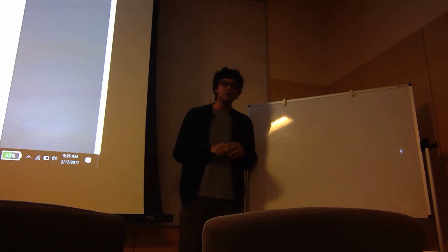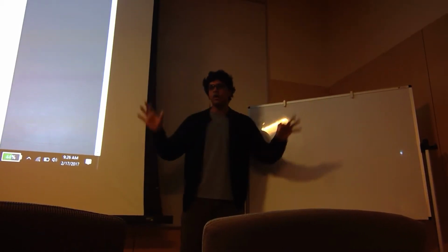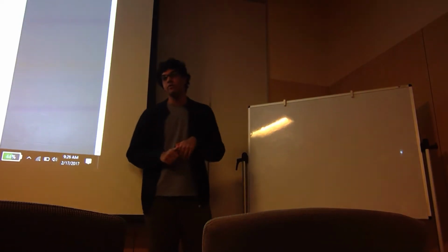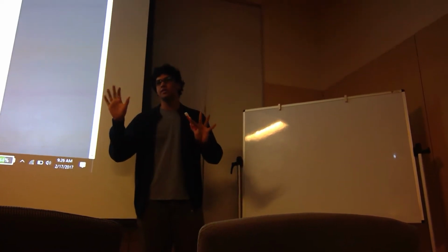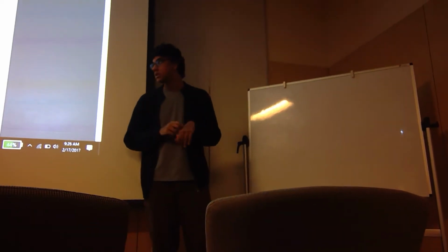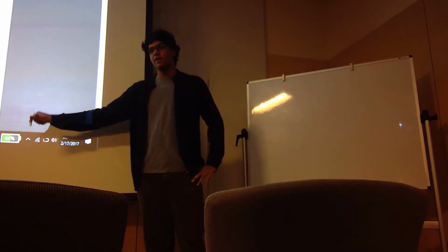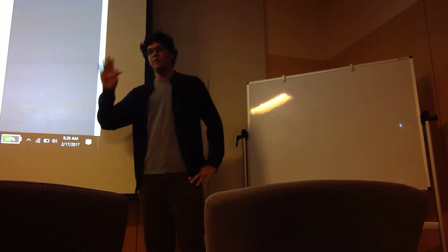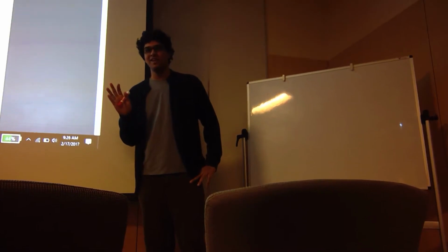Now, usually the layout tools that you use will automatically have a design rule check. It will also have an automatic drawing tool, so it will make sure that when you draw, you follow all the design rules, and then it will automatically check your design rules. But because of the software right now, we don't have access to the 45 nanometer PDK for the design rule check, so you're going to do this manually, okay?